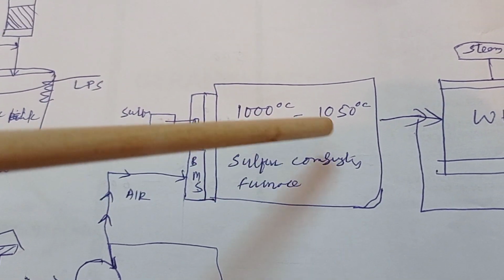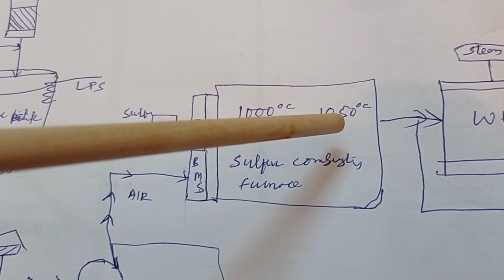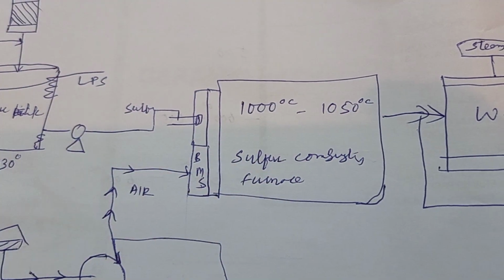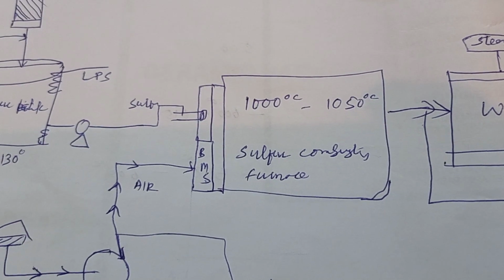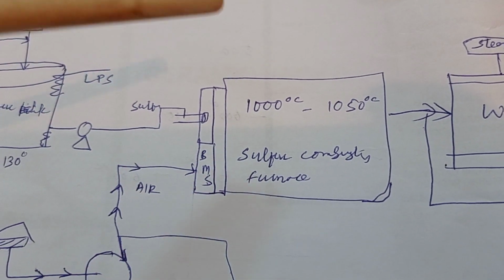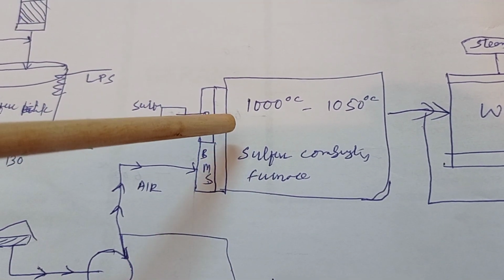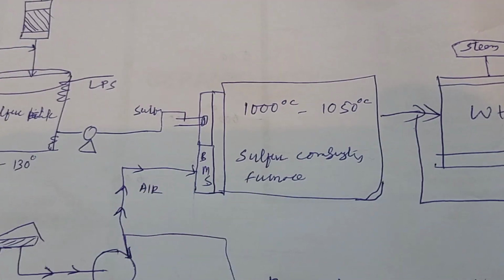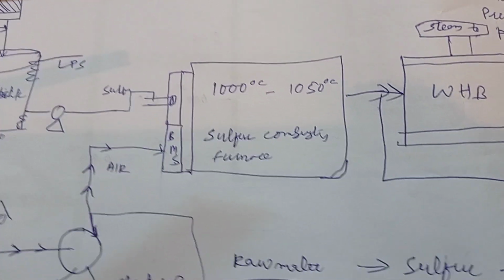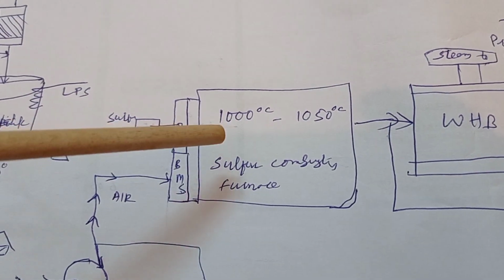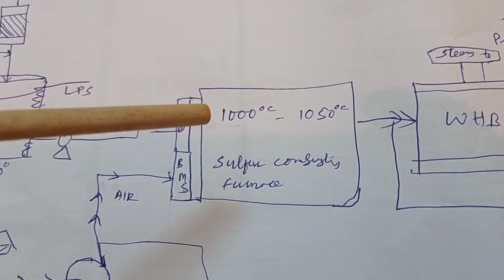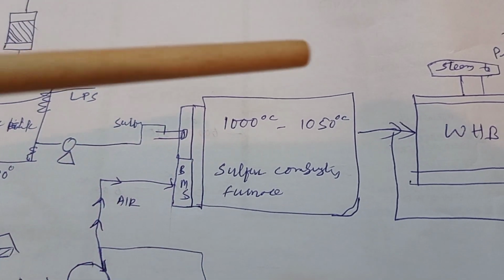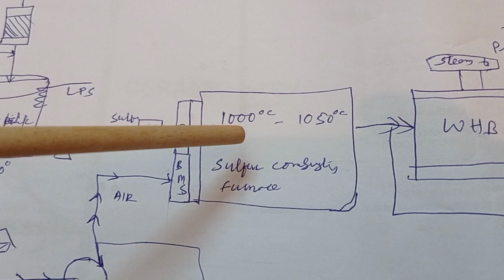And you know how we raise the temperature, by steps, depending upon the refractory. The person who arranged the refractory bricks inside will give us the holding time for the brick, because if we increase the temperature suddenly from 0 to 100 and 100 to 500, the brick may crack. For this reason, we should raise the temperature slowly. We have what are called heating curves. According to the heating curve, we heat the furnace with the help of fuel gas.